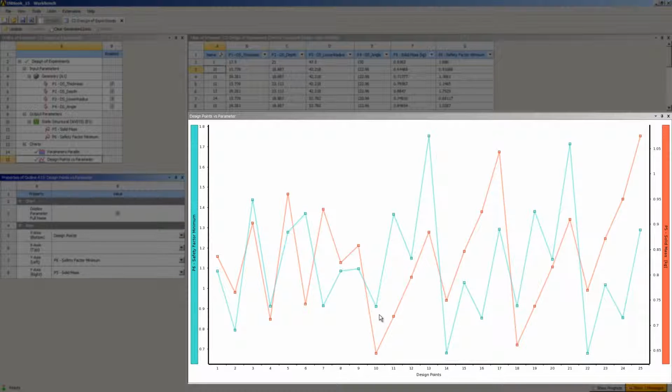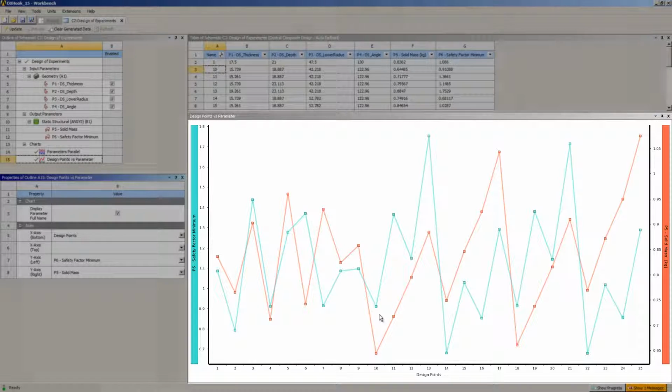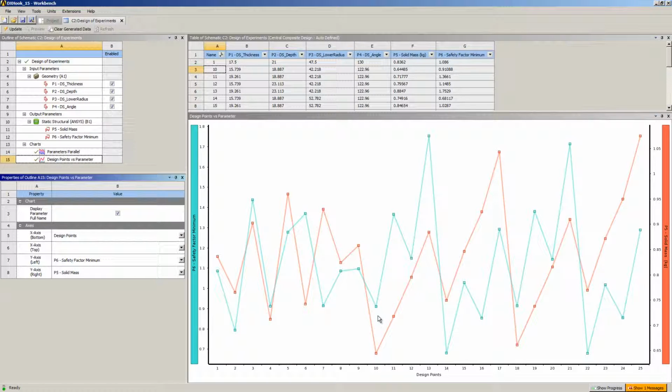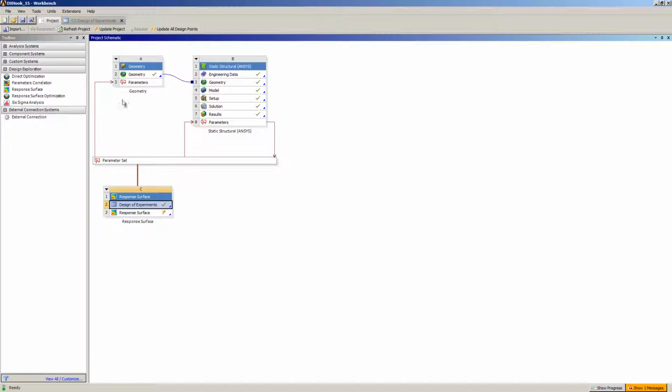The problem gets even more complex when I consider all the inputs and their ranges of variation. Even if I know of one combination that meets my requirements, there may be an optimal combination that I'm not even considering. In this case, the DOE has fallen short of predicting the behavior between the samples. It's difficult enough to use the interpolations to find an optimum with only one or two outputs. It becomes even more difficult with additional outputs, or when you consider the inputs as well. The purpose of the response surface is to interpolate the values in these multiple dimensions.